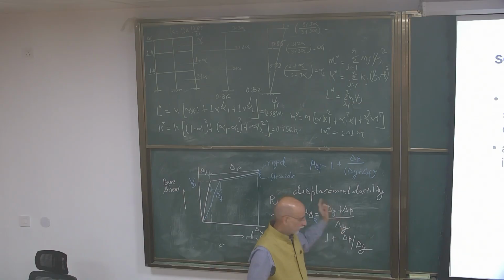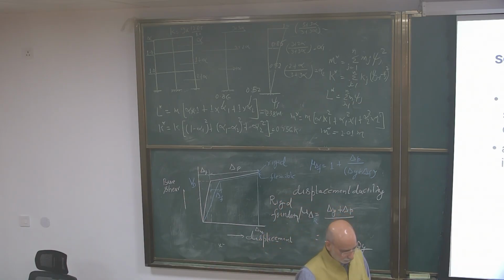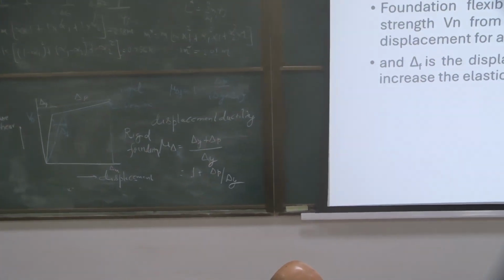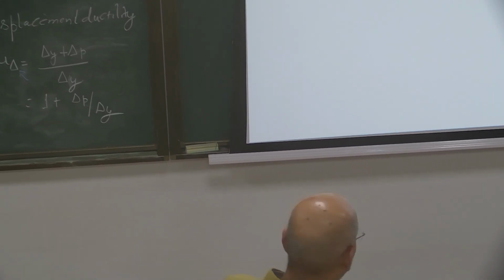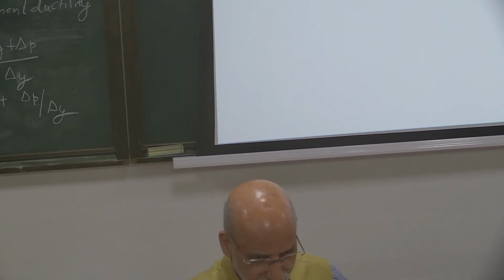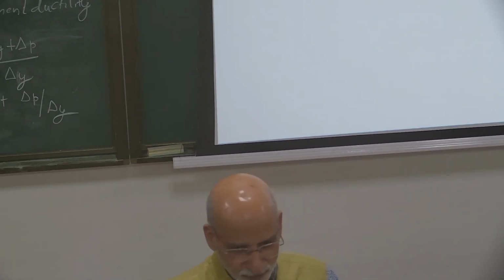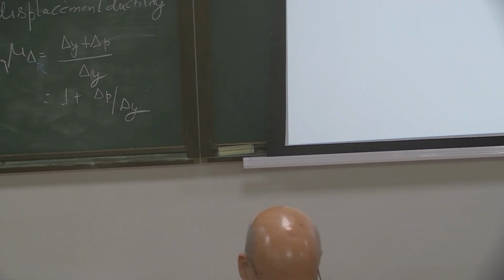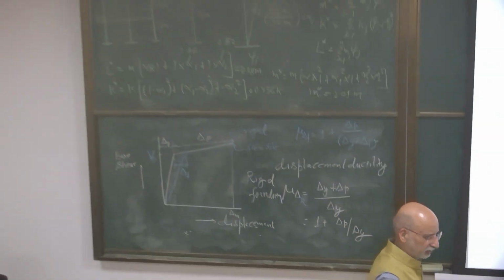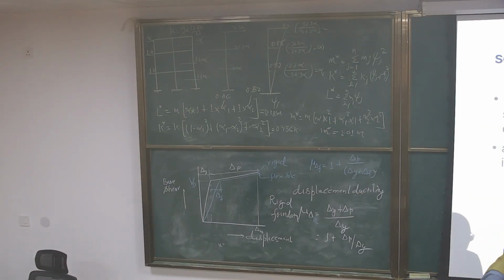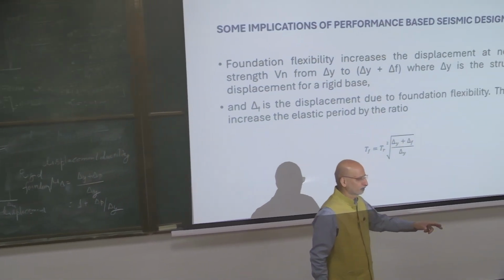That's all. This much is the only extension I wanted to show, of how the ductility is calculated. Ductility is not precisely a displacement. On the force-deformation curve you plot, the first yielding is delta Y. In between delta M and delta Y, the deformation is your plastic flow, that is delta P. The ratio you calculate will give you how ductile the structure is, that is, how much margin is available to allow deformation in the structure.